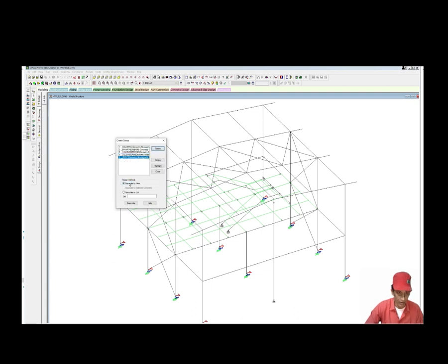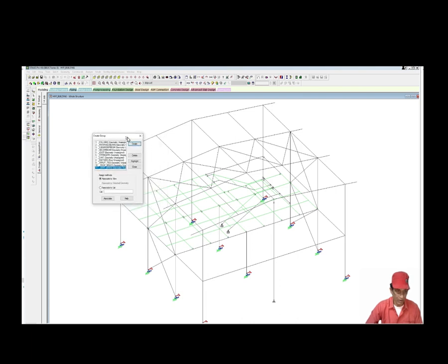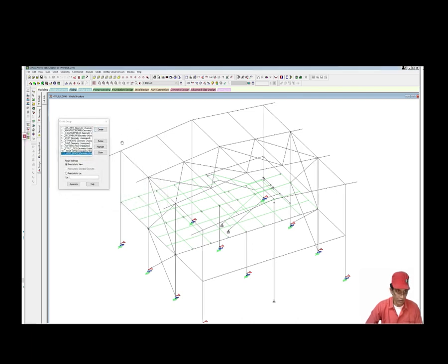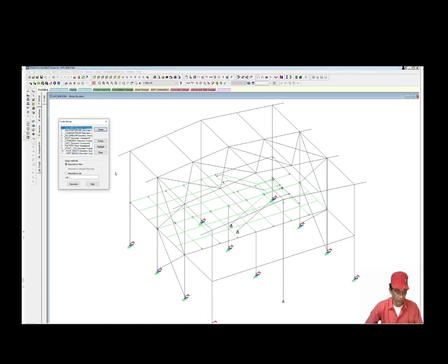Similarly all other groups are created. We have all the geometrical group names defined now. We have column, main beam, main fixed beam, main simple beam, secondary simple beam, joist, stringer, cantilever, rafter, strut ties, roof bracing, and vertical bracing. So let us assign these groups one by one. Let us go to column.